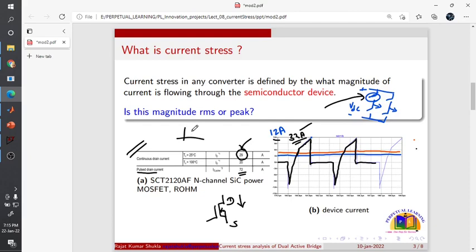Pulse, that means it would be, you can say whatever the current is in this portion, and this is suddenly peak till 72 ampere. It has a capability of 72 ampere in a very small time, right? So I'm not saying it should be 72 ampere, otherwise the device may get damaged. But just try the peak value to be near the continuous drain current rating. Then the device will perform very well.